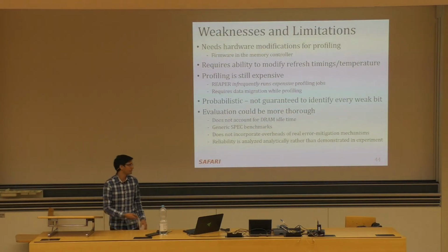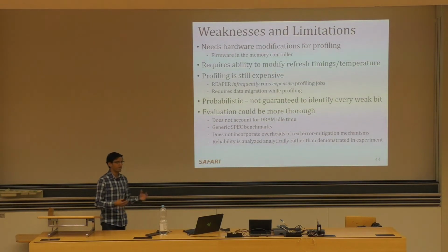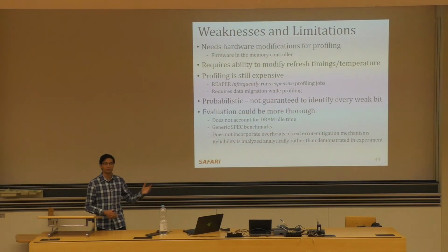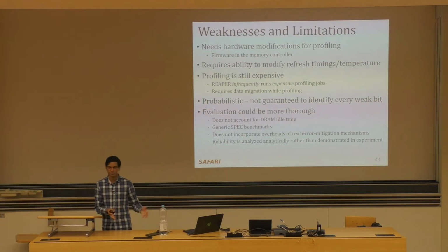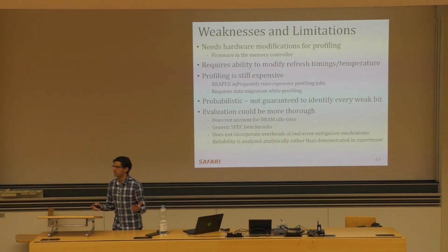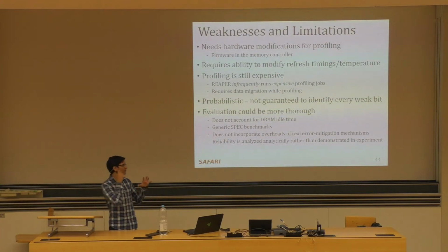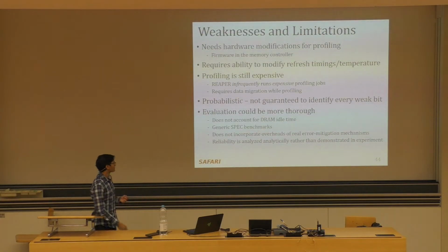And similarly, for the power measurements, for the power evaluation that I showed earlier, we showed that this has significant power benefits. However, if the DRAM is constantly idle, it's hardly burning any power at all. And so the power overhead will be significantly more.